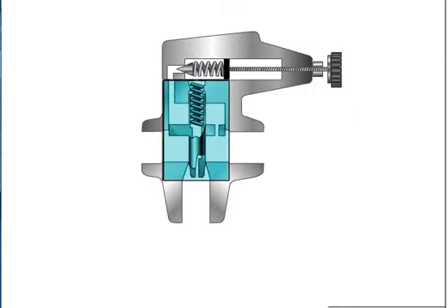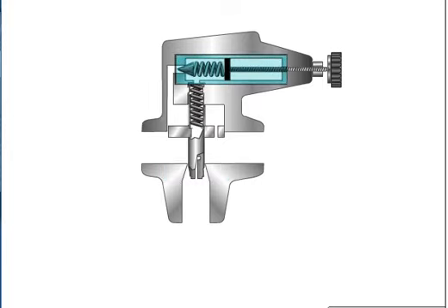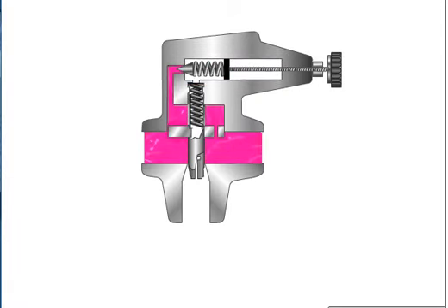The second stage handles full rated flow to the tank. The first stage controls and limits pilot pressure level in the main chamber. Relieving action through the main spool is as follows. As long as the system pressure is less than relieving pressure set on the control knob, pressure in the main spring chamber is the same as pump line pressure because there is no flow through the control orifice, and consequently there is no pressure drop from one side of the orifice to the other.